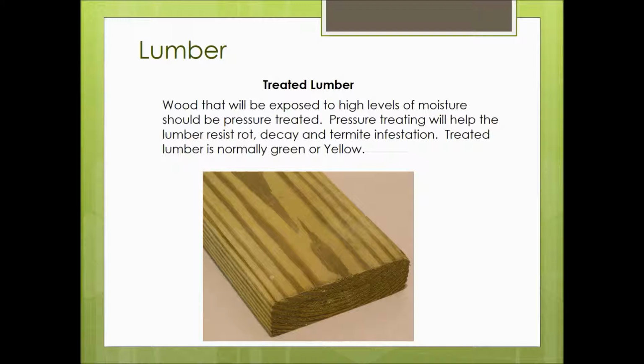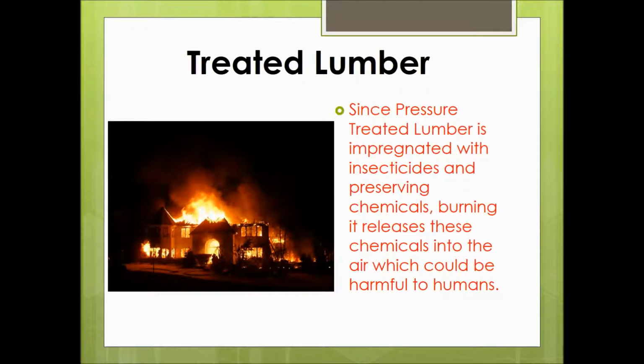The reason we're talking about this right now under the safety heading is because when treated lumber is burned, it releases the preservatives and insecticides into the air. So if you are around treated lumber and it's being burned, you are breathing in that smoke and you're breathing chemicals into your body. So if you're around treated lumber, don't burn it. Just throw it away. Let them take it to the dump. It's much safer to do that than it is to burn it up.